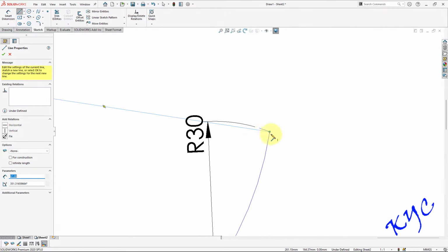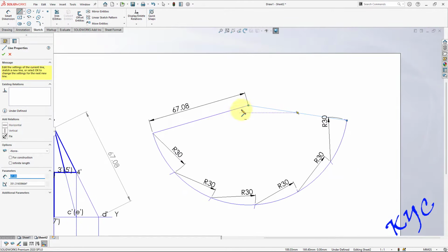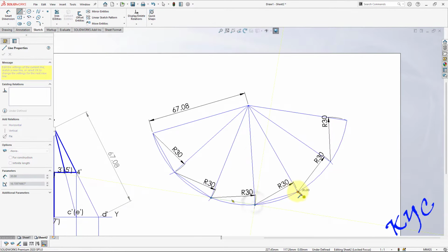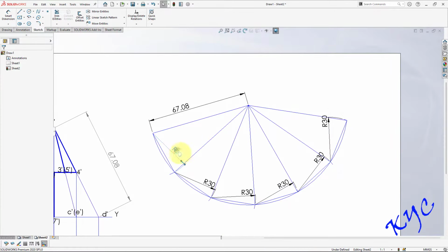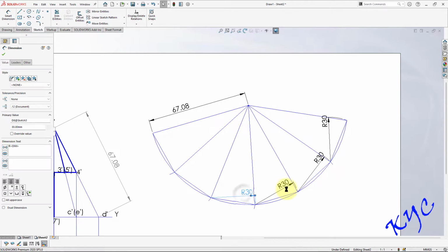Okay, don't connect to the arc, connect to this portion of the arc. Then you join to the centers of the circle. Okay, after this, connect this to this. This becomes the base of the triangle, which is 30 mm. All triangles will have a side of 30 mm now. This is 30 and this is the slant edge. After this, you can delete the dimensions, not required.